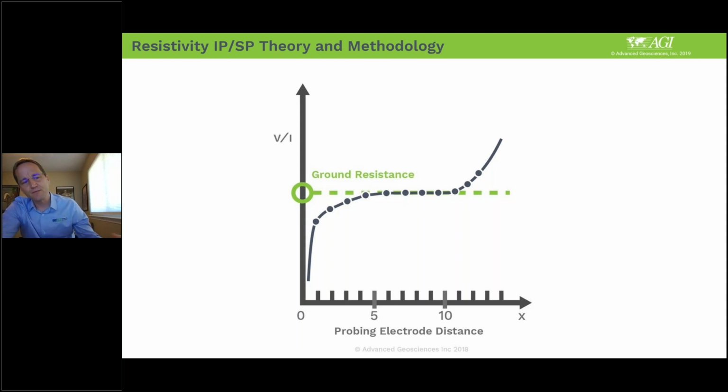So if you're approaching a perimeter fence, which is essentially short-circuiting what you're trying to measure in the earth, you'll see a non-characteristic curve, and you can account for that potentially by moving where you're doing that FOP test, or at least mention it in the report, because there will be some doubt as to why the curve didn't rise as you approached that C1, or you have an inflection in the middle, something along those lines.